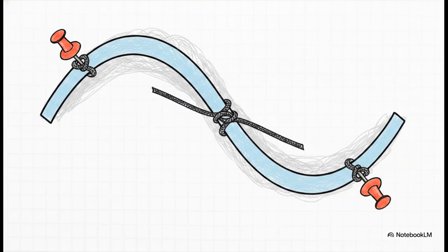So you might be wondering, why go through all this effort? Why not just stick to a simpler model? Well, because doing it this way mathematically guarantees that your resulting transfer function perfectly matches the real system's response at those discrete chosen points. You are literally forcing the mathematical model to tether itself exactly to the reality of the physical system at the 33% and 67% marks. It ensures an incredibly robust, rock-solid fit.